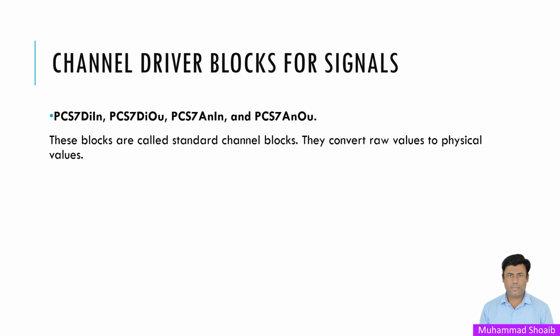So the PCS7 digital input, digital output, analog input, and analog output channel driver blocks are called standard channel blocks. They convert raw values into physical values.